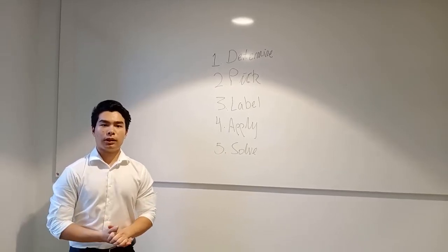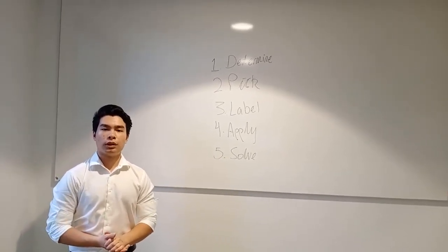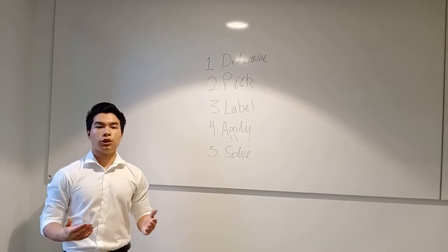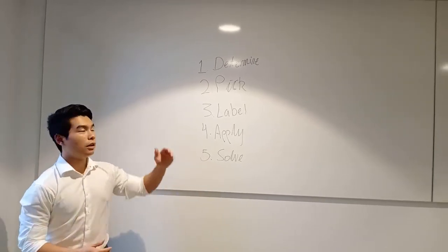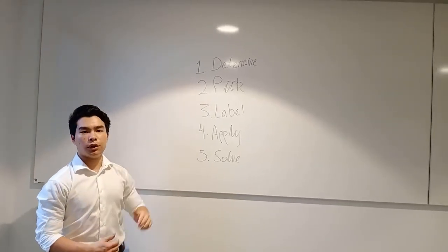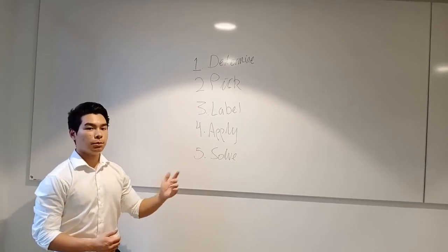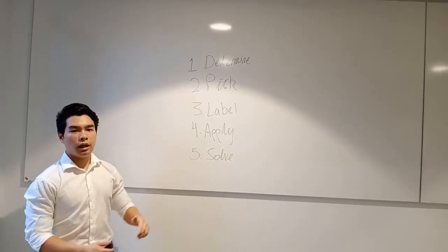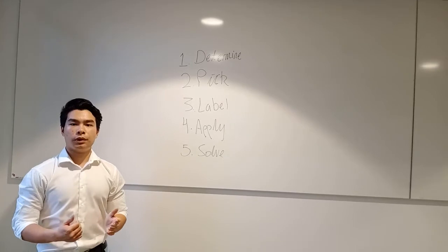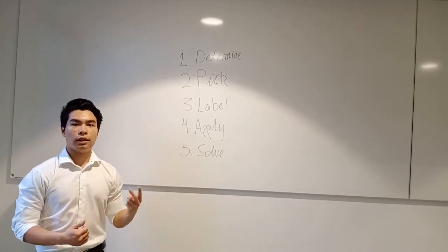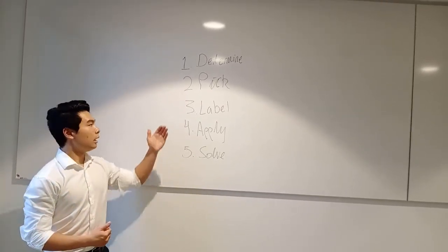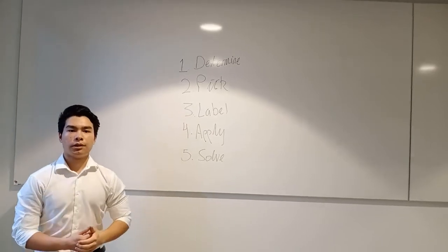When utilizing nodal analysis to solve for the unknown voltages, there is a general procedure to follow shown here. Step 1. Determine the number of nodes within the network. Step 2. Pick a reference node and label each remaining node with a subscripted value of voltage, V1, V2, and so on. Step 3. Label current directions and polarities.